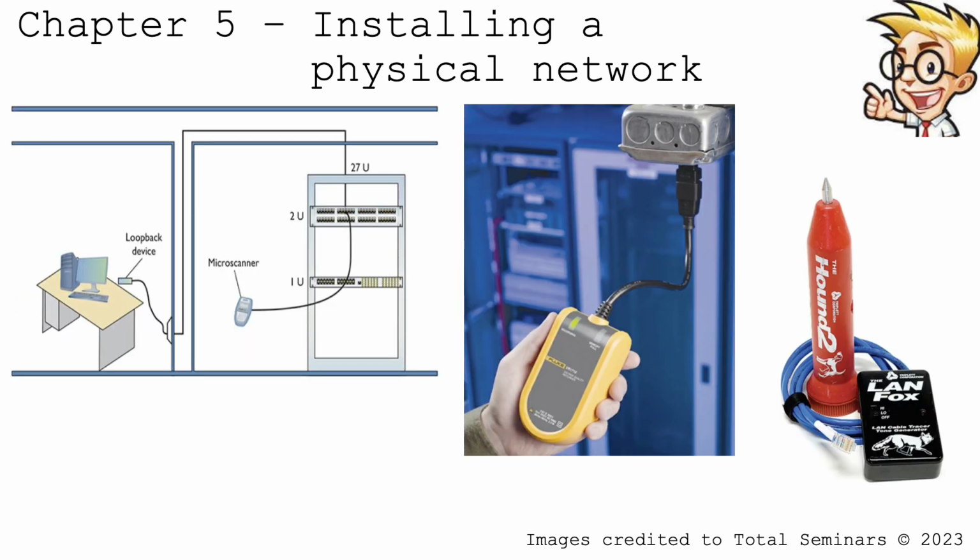Okay, and we're on the last slide here. Here's an example of a loopback adapter in action. So we can actually see if this loop device is working correctly. We can use a scanner to send a signal, and if it comes back, then we know it's good. If it doesn't, then we can further isolate, is it the cable, is it the loopback, or keep going.